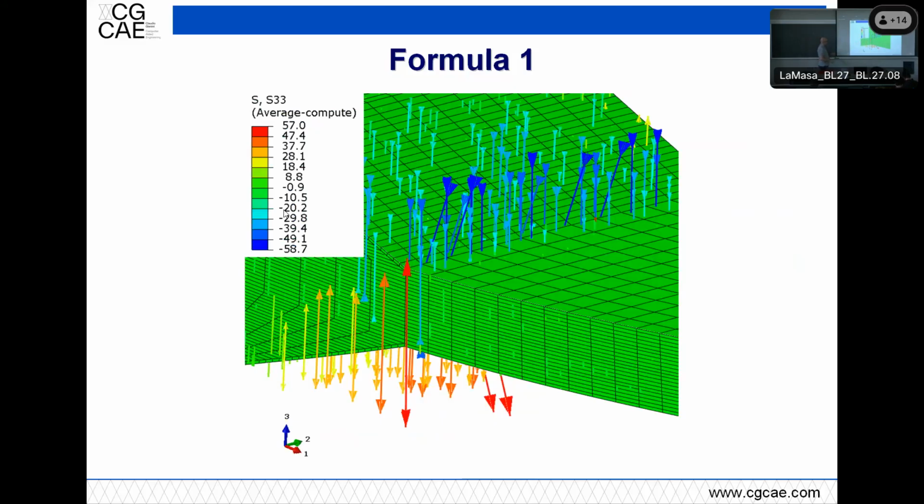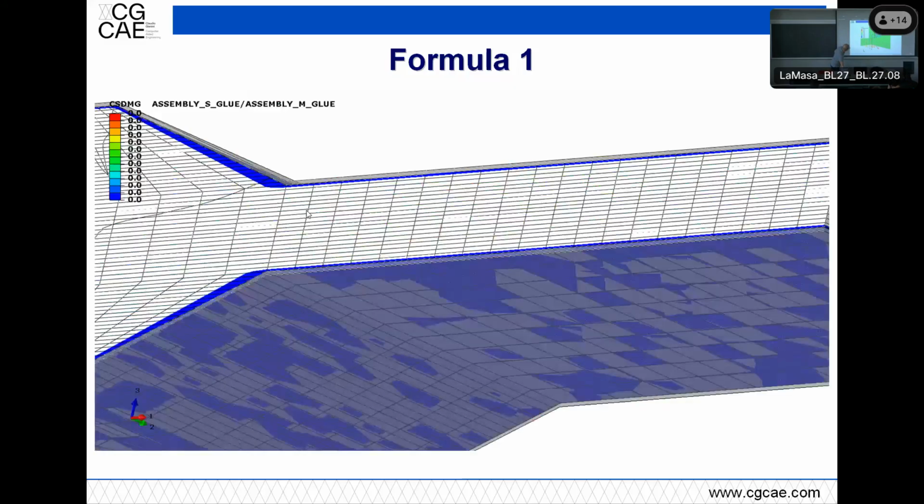The funny thing was that the previous year was very similar. So this ramp was slightly smaller, and the excursion, the travel of the suspension, was smaller. These two things together were enough to raise these stresses to the level where it failed.